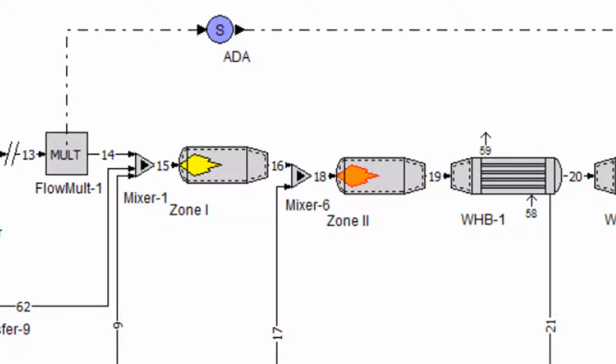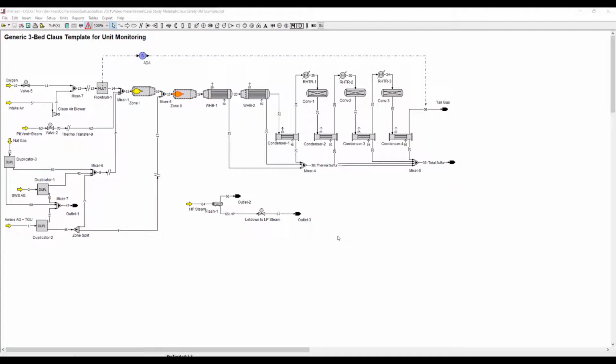The area where refractory failures are occurring was at the top half of the front zone. In OGT's experience, this can be a weak link in the armor of a sulfur plant. The keying of the brick around the head transition can be tricky to get right and requires an engineered solution. This is also the hottest area of the sulfur plant. OGT set up a monitoring system for this plant using ProBot technology that we will switch over to.